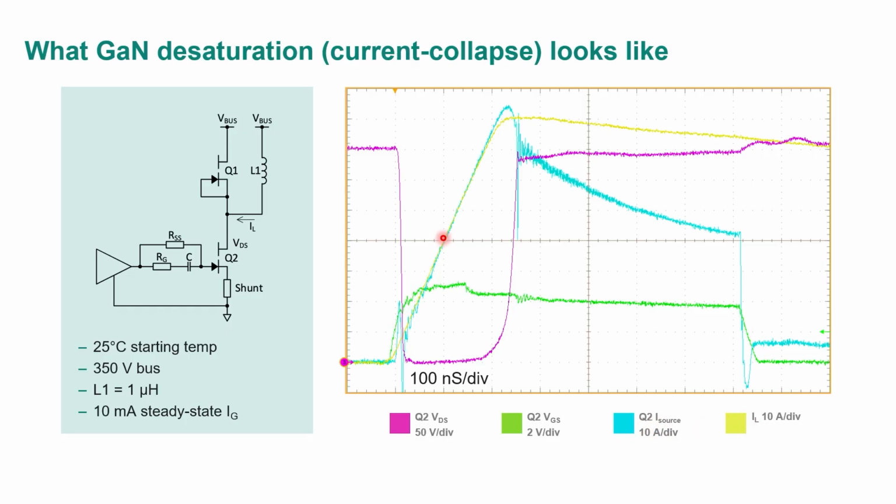They're tracking here at 10 amps per division, so 10, 20, 30, 40, 50, 60, 80, more than 80 amps. I think what you're seeing here is the current probe is starting to saturate, but meanwhile, look at what's happening to VDS. Once I reach about 60 amps, VDS is suddenly starting to exponentially increase here. So you can imagine the power dissipation. If I were to multiply V times I here, it's really getting out of control.